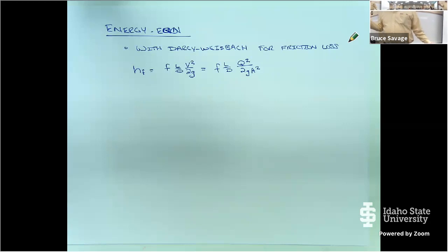It's weird. Why would a spinning pipe, you would think that would have more loss, because now the wall is moving, right? And it's not translating with the flow, it's spinning around. So they started tracking the flow vortices in there, and they found that when you do that, you get these little tiny vortices that build up around the perimeter of the pipe. And in their calculation, that's what allows the flow to go through there easier than if it wasn't there.